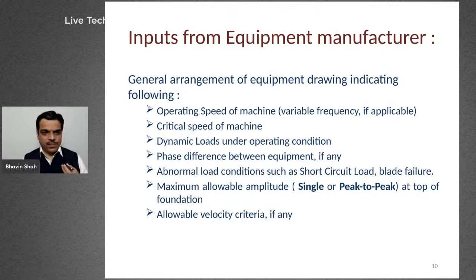At the same time, another machine will be producing force in the minus x direction, and that depends upon what the phase angle is there, and because of that, it may cause a twisting of the foundation. So the phase angle, the phase difference, is very important, and we should put it very carefully into the computer analysis.